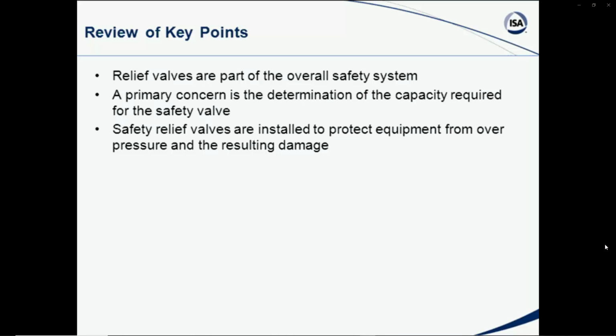But right now, looking at this as part of the overall safety system, you might, for instance, need to put a rupture disc underneath a relief valve that's dealing with a corrosive gas, and that way you can use a more conventional material for your more expensive relief valve while obtaining a very economical price on a rather elaborate rupture disc.